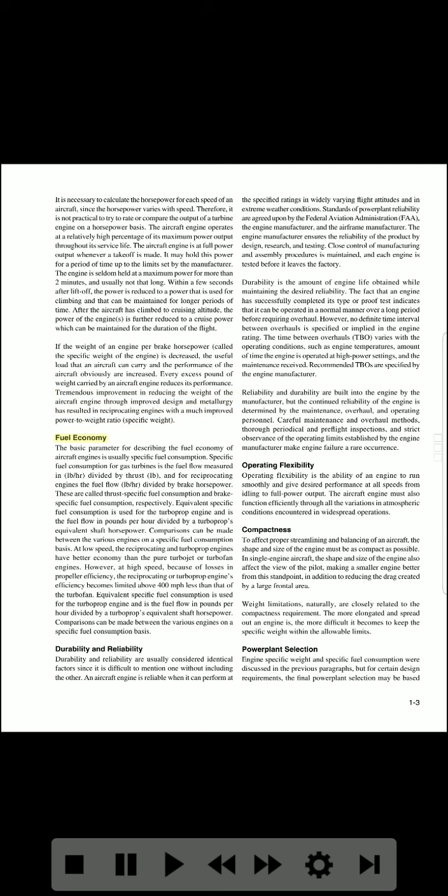Specific weight. Fuel economy. The basic parameter for describing the fuel economy of aircraft engines is usually specific fuel consumption. Specific fuel consumption for gas turbines is the fuel flow measured in pounds per hour, divided by thrust, pounds, and for reciprocating engines the fuel flow, pounds per hour, divided by brake horsepower. These are called thrust-specific fuel consumption and brake-specific fuel consumption, respectively. Equivalent specific fuel consumption is used for the turboprop engine, and is the fuel flow in pounds per hour divided by a turboprop's equivalent shaft horsepower.